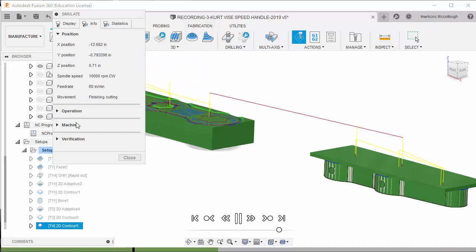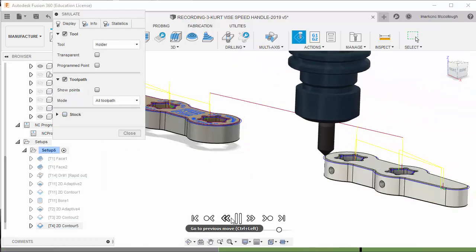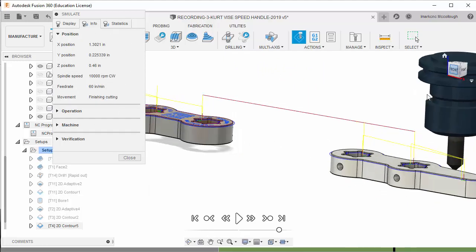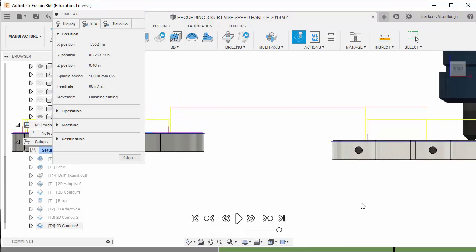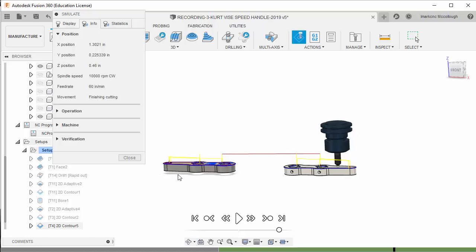Now the material shows like this, so I could turn off the stock so you don't think that I didn't remove the stock, but let me stop it. And you can see that this height is at 46 because the parts are not at the same height. They're in different places in there, but the tool adjusts because I told it where to go. My Z0 is right here, but I'm telling it exactly every place it needs to go. And as you can see, that works fine.